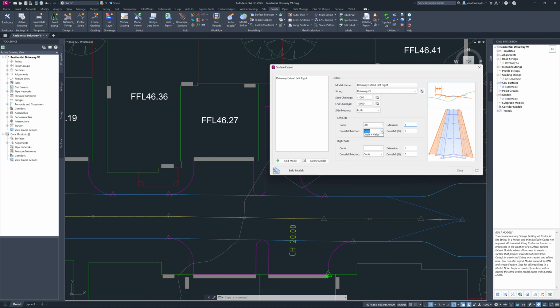It can do one of really 3 things, but the two main ones are this. It can actually take your slope of your left edge of bitumen and project that out. So if your slope happens to be positive or minus 135%, whatever it is, you can extend that out by 1 meter. You can also nominate your own value, which is what I want to do. I don't want to change the elevation as I'm beginning to move in and match onto my road design here. I want it to be exactly the same. So I want a 0% crossfall. I'm going to do the same on the right-hand side. Value 0 and an extension of 1 meter.